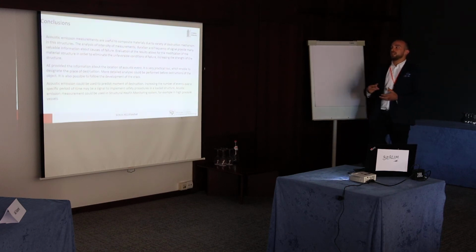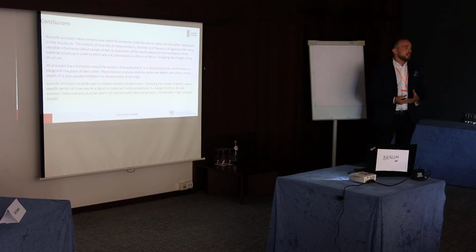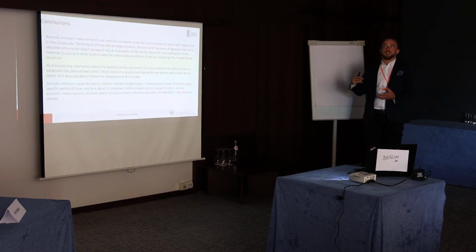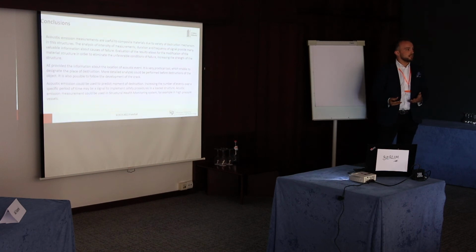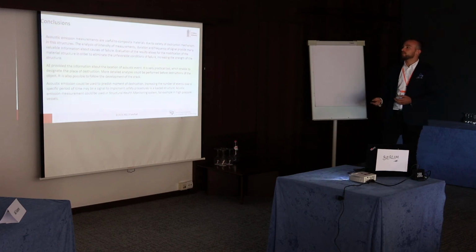Acoustic emission can give us the location of the failure. It is really important when we try to find delamination in our composite, or, for example, in pressure vessels, when we try to detect a leakage.